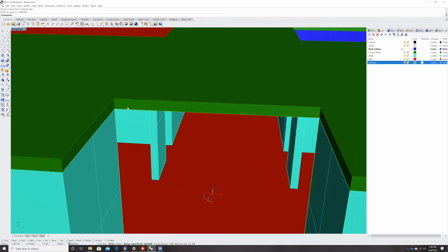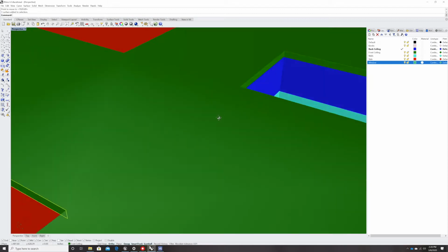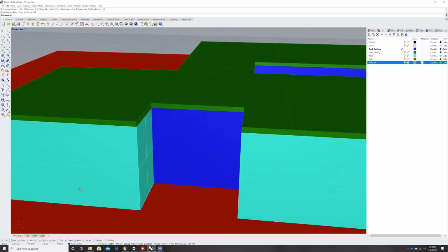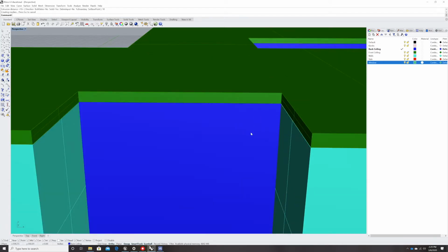And then I'm going to actually sub-object select this and move this inward 10 inches. So if I control shift and click on this, it gives me this object selected by itself, and then I can click on this and go -10. Okay. And then I'm going to extrude this direction 10. So my window now is perfectly in line with the walls.